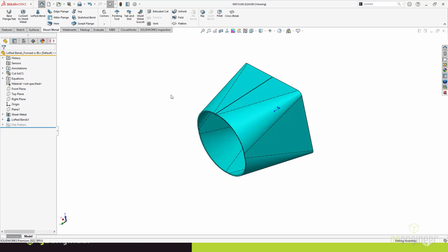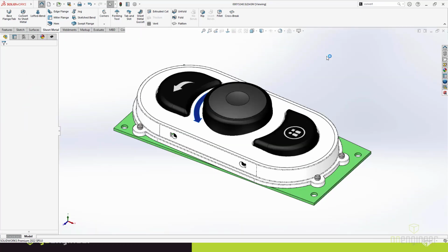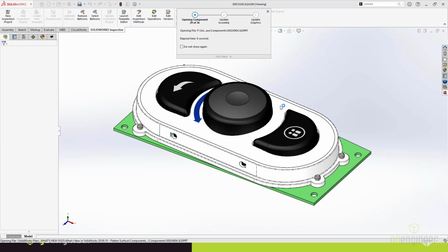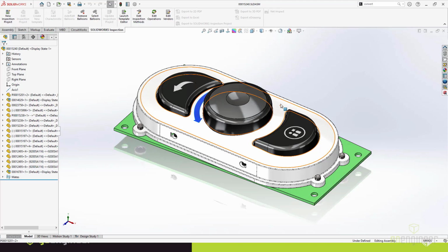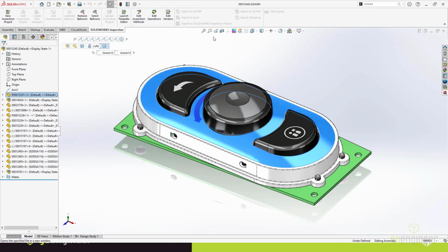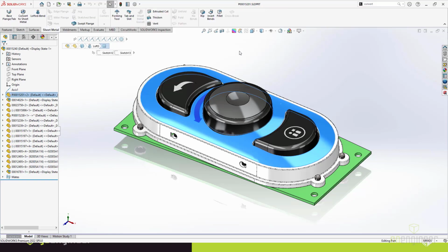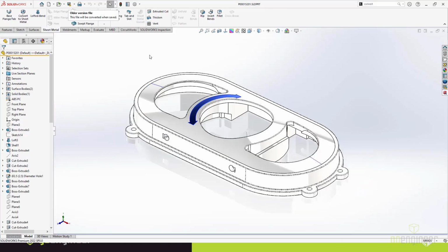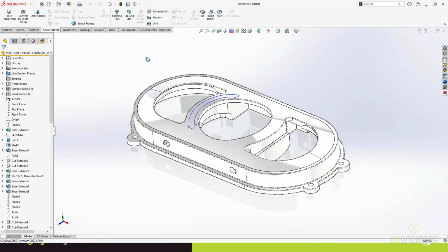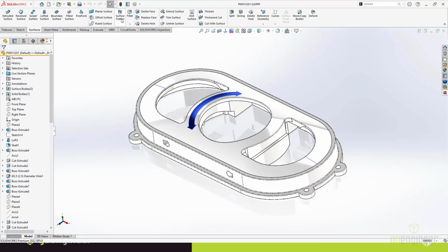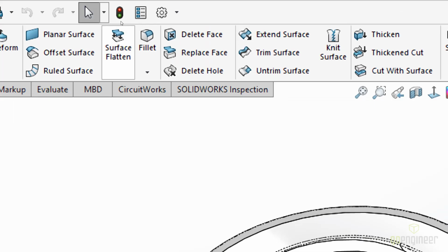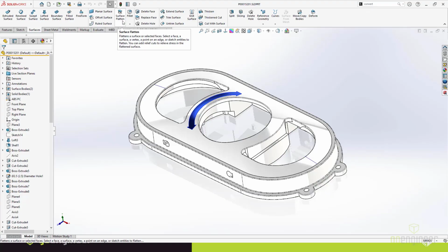So if you do have access to SOLIDWORKS Premium, you can get the flat pattern of pretty much any geometry that you've created. Now, I say that with a little bit of hesitation because we have a third-party product called Forming Technologies that is for stamping dies. It's for doing door panels and one-hit type operations with draw beads and binder plates and all kinds of great stuff. But when we're talking about this one here, this tool is called surface flattening, and it only exists in a premium seat of SOLIDWORKS.